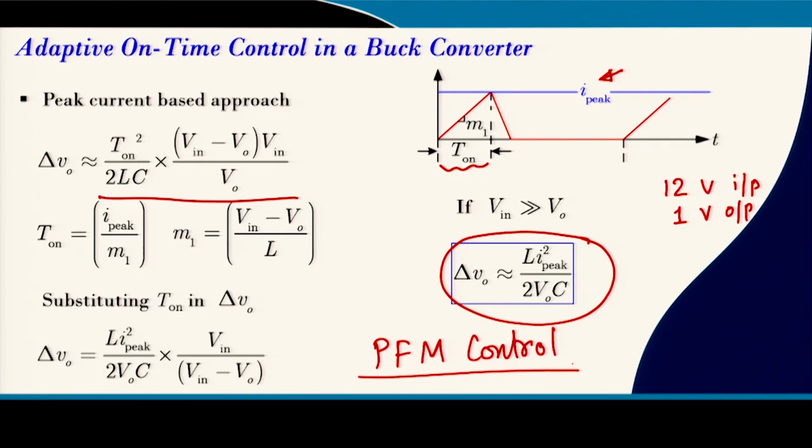Under fixed input voltage the on time remains the same, because none of these quantities are changing. So, it retains the linear variation with the load current. Under variation in input voltage, it retains the ripple information, that means the ripple is constant. This is used in many commercial products, and we will discuss other adaptation methods.